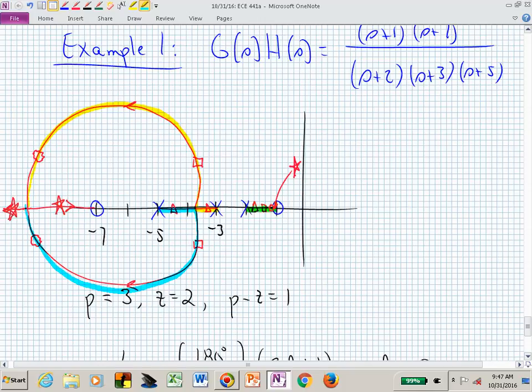And it doesn't matter if you keep track of which branch is which, because they're going to appear as complex conjugate pairs. So this guy, maybe the blue, since I'm still blue, he might come back to -7. The yellow, he's adventurous. He goes off to -infinity. So there's one branch that goes off following our asymptote, and in that case it is right on top of our asymptote, the branch. The other branch goes from wherever we re-entered, which might be -12, and zips back to -7.